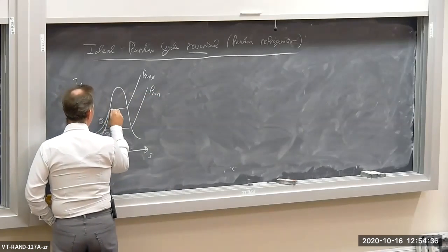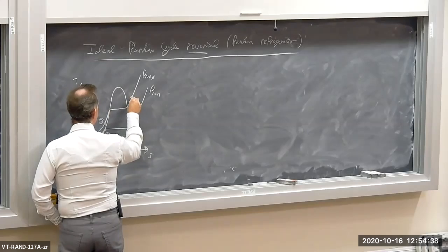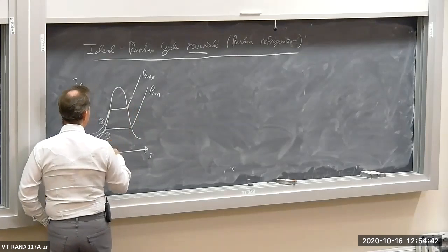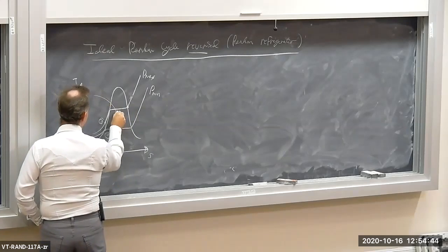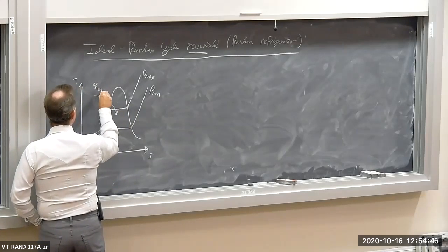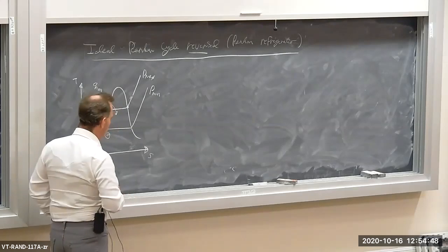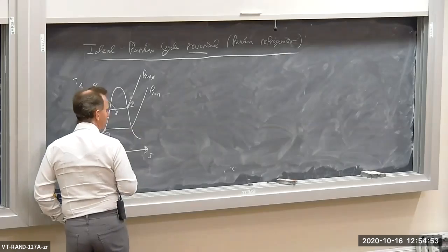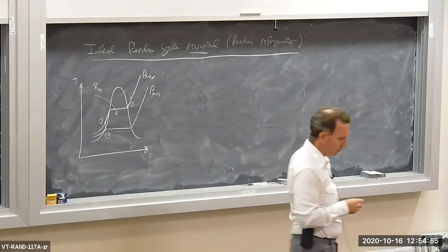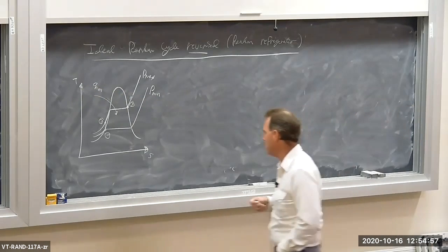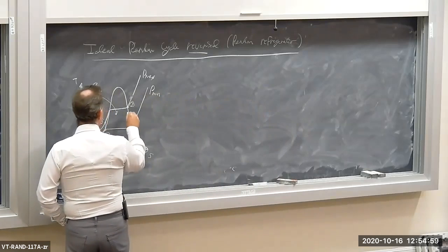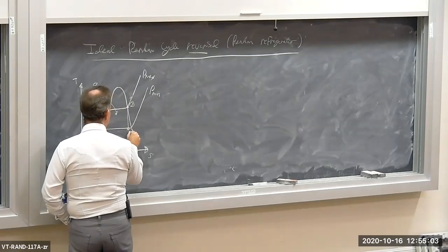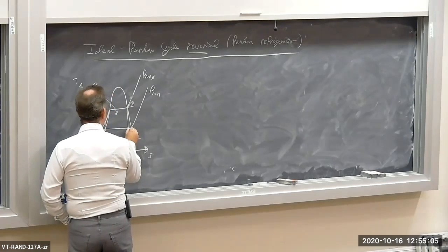And then, of course, we add heat. So here, this is an ideal cycle. So we're adding heat here in the boiler, Q in the boiler. State 3 is a saturated vapor at the maximum pressure. This is the ideal Rankine cycle. And then, of course, we expand isentropically, reversibly, adiabatically expand the working fluid in a turbine.